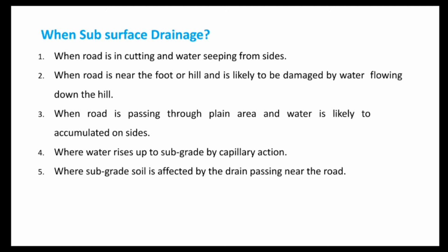Third, when the road is passing through a plain area and the water is likely to accumulate on its sides. As this water may percolate into the layers of the pavement, it can lead to its failure.